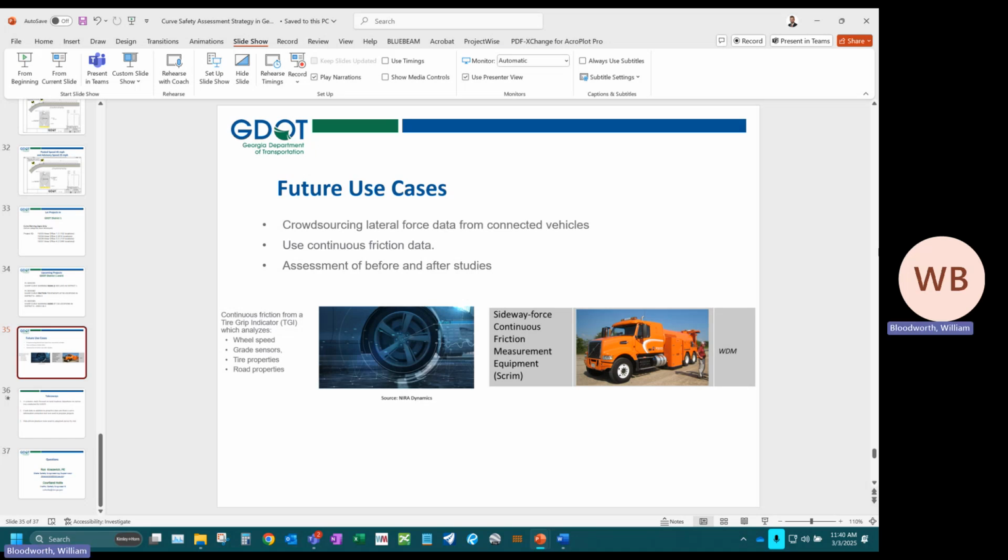Right, so the question is, when you're dealing with preemption, can you coordinate with train schedules? And the answer by and large is no. You can try to coordinate with the railroad to get train schedules to maybe coordinate how you respond to preemption with the train equipment. However, train schedules are fickle. That's what the railroad will tell you, that there's not general consistency. So you can perform your own analysis and make your own determinations on when trains will and will not come, and you can use it, but you won't be able to get something that confirms or denies that.